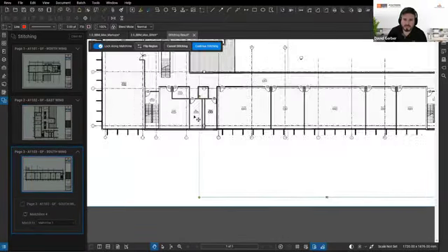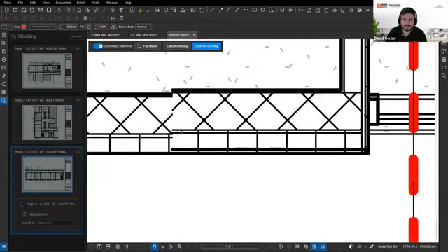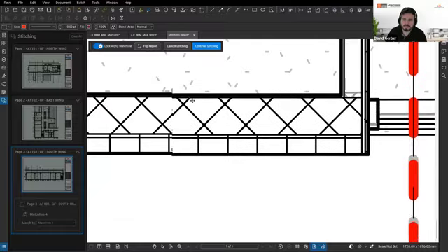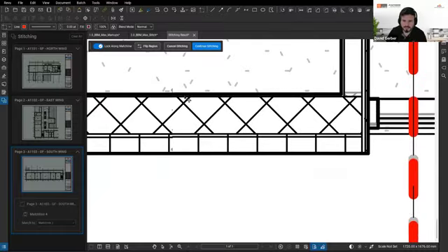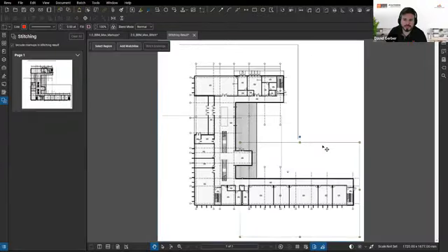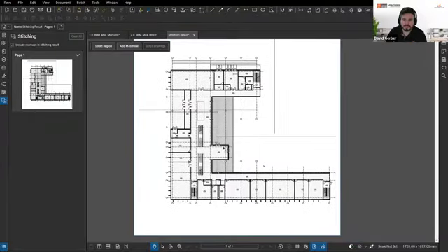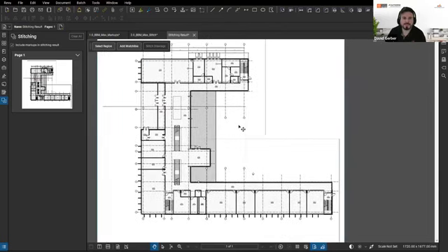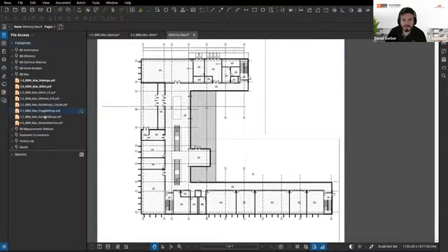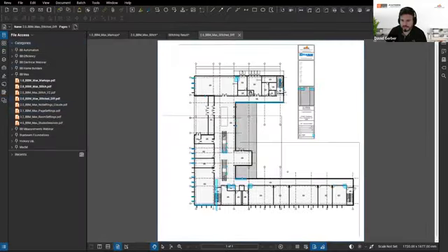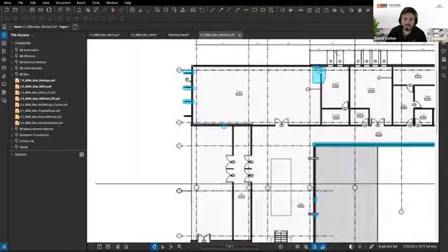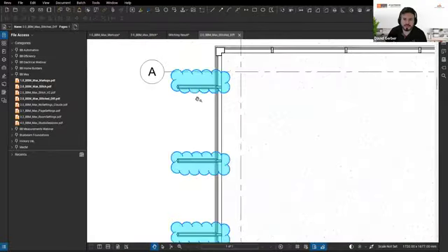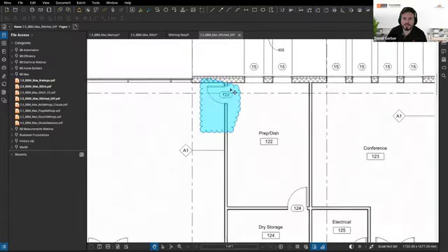So if I zoom in, you'll see I was slightly off. But the good thing is as I start to move it, it won't go left and right. It'll only stay up and down, or depends on your match line, obviously. But then I could just continue stitching and say, hey, I've got that done. So you can really see three of my drawings of my building are stitched together relatively quickly. And then I can go and compare it. I can overlay it. So I've already finished one. So you can see that here. Obviously these, maybe they moved, maybe they didn't. It could have just been from me not doing it great.